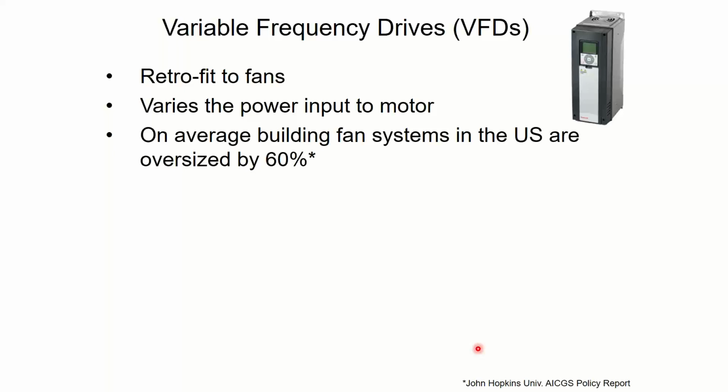Fan systems in general are oversized by 60% in this country, which is astonishing. I have seen plenty that are double the size they're supposed to be. I've never seen one that wasn't at least a little bit oversized. So kind of our discussion like we had with cooling sizing, fans are in the same boat. They're all oversized and many are grossly oversized.